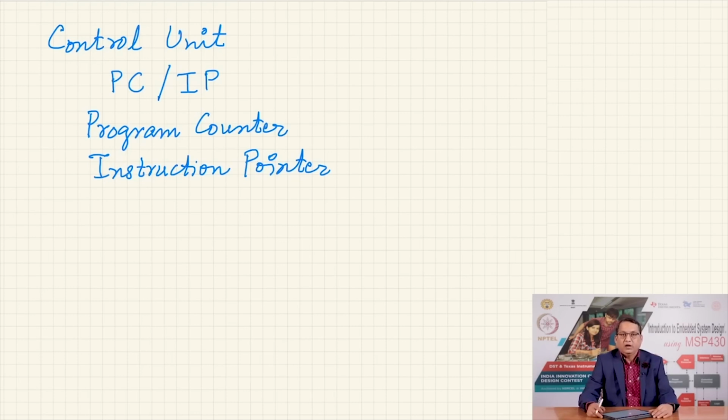This is nothing but a few flip-flops arranged together to provide the initial address when the microcontroller is reset, right. Now, if the value of these flip-flops take arbitrary values, that would mean that after reset the microcontroller at some point may go to a certain memory location to fetch the first instruction, at some other time it may go to a different location, and if that happens, you will never be able to execute your program properly.